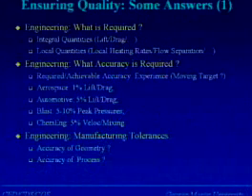If you think about blast, I may not even know the mixture of the explosive that has been used in a terrorist attack to a certain degree of accuracy. So I cannot estimate the TNT equivalent, which means that 5 to 10% peak pressure is already extremely good. And if you think about chemical engineering or all the other possible industries, food industry, all the other industries that have a lot of variability, then engineering will tell me what is the accuracy that I need. Then you have to look at the manufacturing tolerances. What is the point in having the geometry defined to 10 to the minus 6 if I can only manufacture to 10 to the minus 1? So perhaps you are, as the saying goes, barking up the wrong tree there.